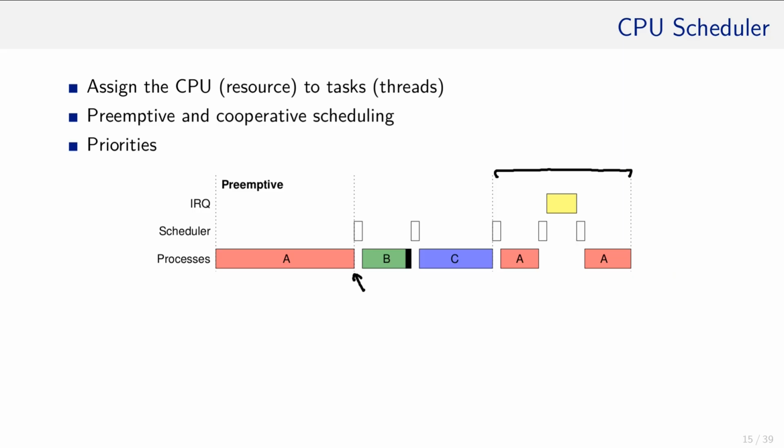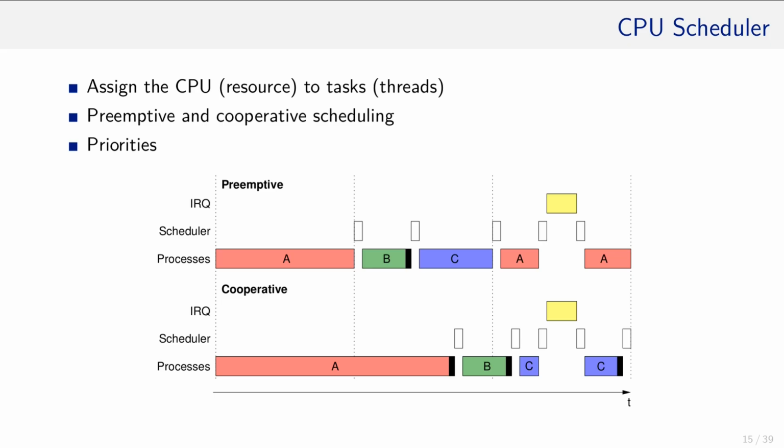Managing all this is the responsibility of the scheduler. Obviously, optimizations can be applied. For instance, if a task does not need all registers, those unused registers do not need to be saved. It is different when compared to the cooperative scheduling policy shown below.